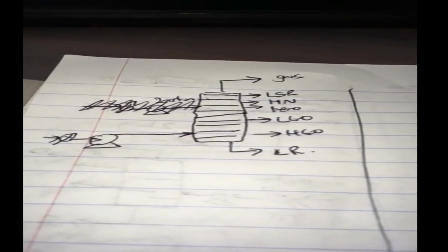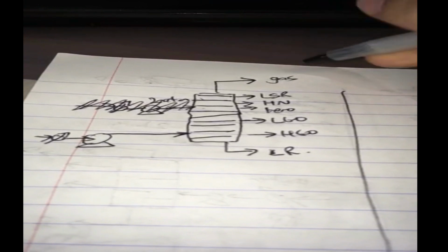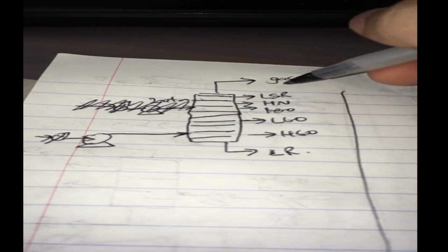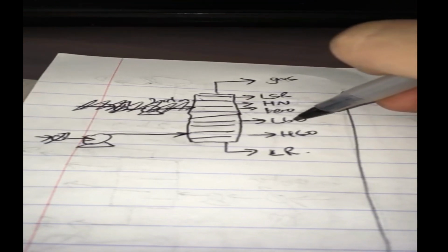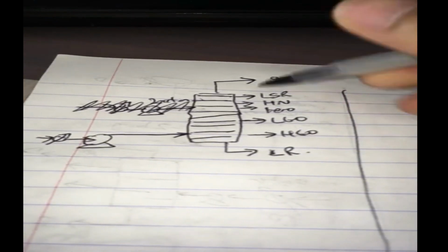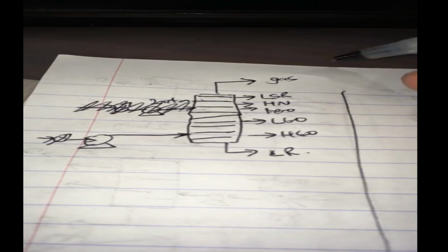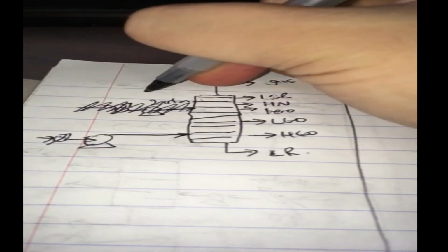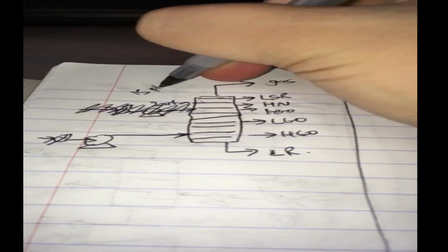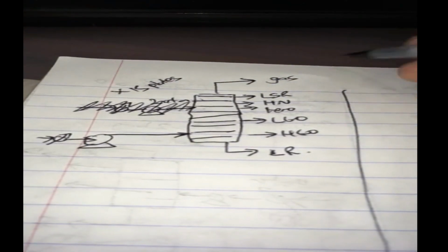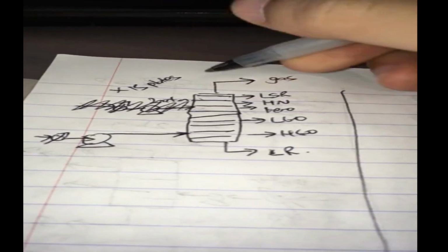Okay, so now we need some reflux to the tower to perform controlled cooling. And we also know that if you actually draw these fractions off, it will not be very pure, heavy gas oils or kerosenes or something like that. There'll be still lots of light stuff in there because you have to go up the plates, and this will not be 15 plates. This is not 15 plates because it's the separation. You need it to be very good. So we're talking about separations here. We need very good separation.